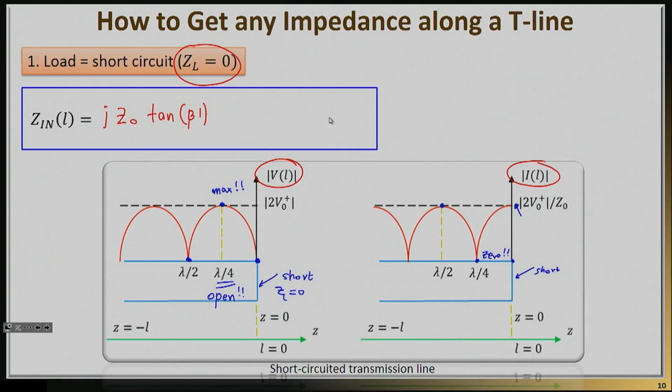Now, of course, when you were taking undergraduate courses and designing circuits, usually those circuits were at very, very low frequencies, which meant that lambda was a very large number. If you're designing a circuit at 1 megahertz, lambda is really large compared to the physical dimension of your circuit, so you will never see that effect. But when lambda starts becoming 1 centimeter, 1 millimeter, then very quickly, unless you're very careful, you can run into trouble.